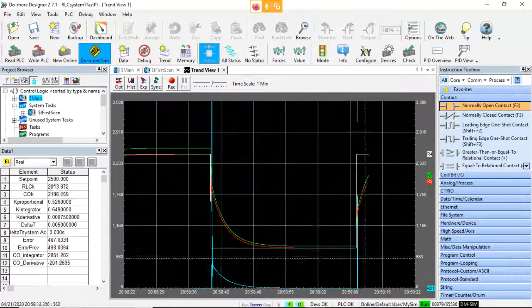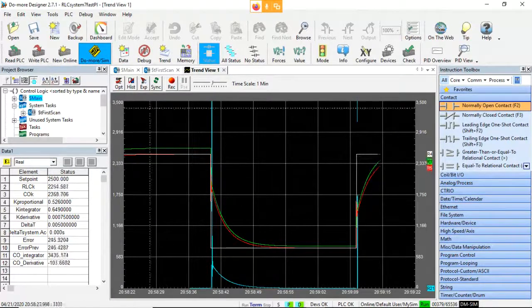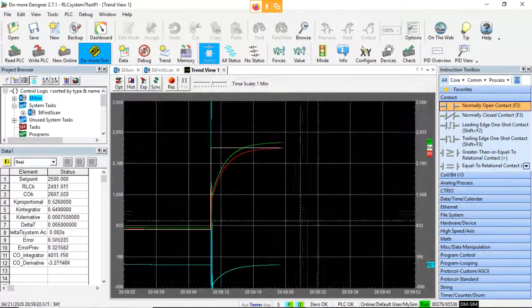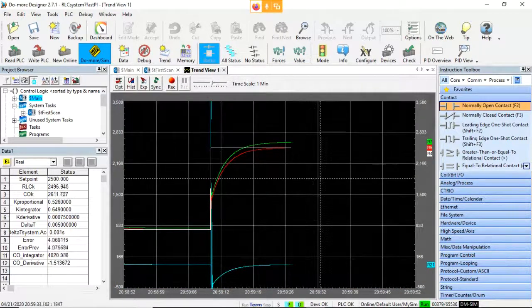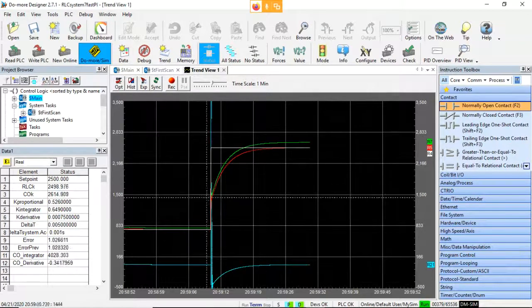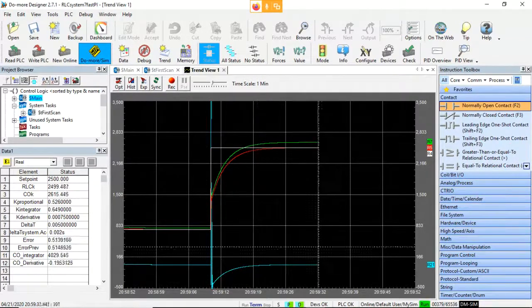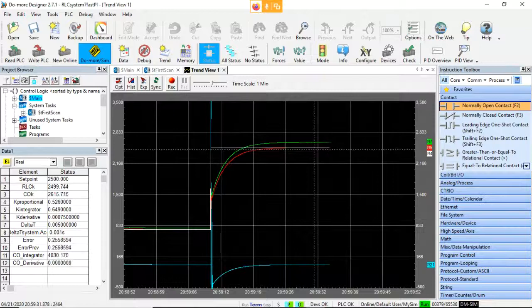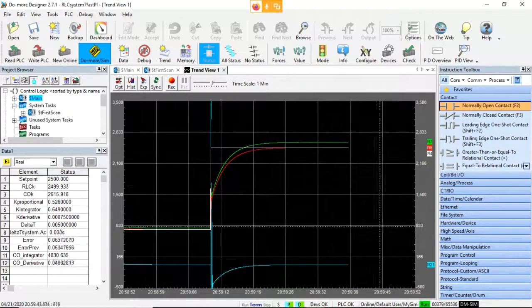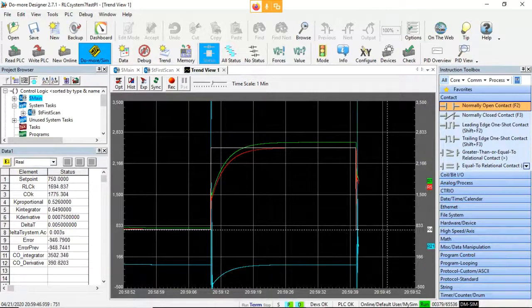So there's some negatives in here too. If I extend my scale to a negative minus 500 maybe, and see if that goes negative, okay, when it toggles, because this thing's bouncing, remember it's ringing here, the derivative is going positive one time and the next time it might be negative. And so you get this huge bouncing around of the derivative piece.